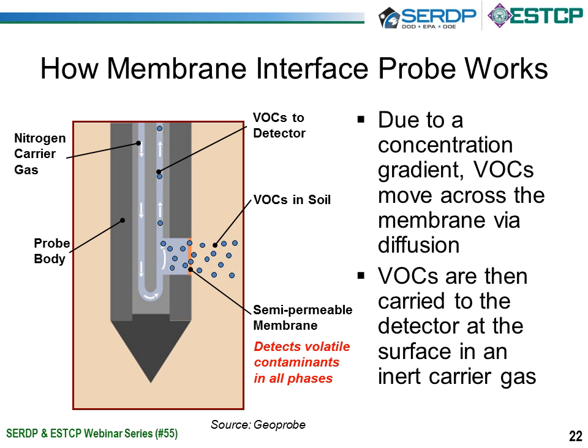So if I want to know where there's NAPL or confirm that there is no NAPL, the membrane interface probe is not going to tell me that. It's a very useful tool, but I tend to use it more for dissolved phase investigations.